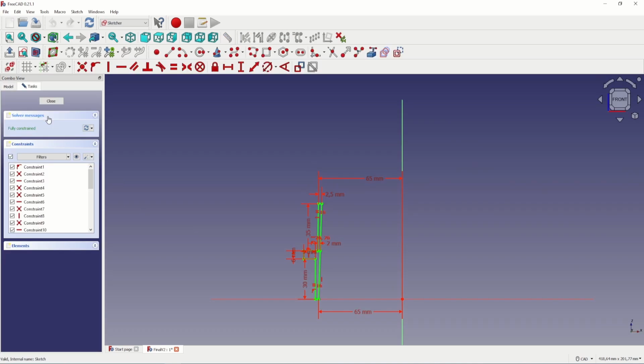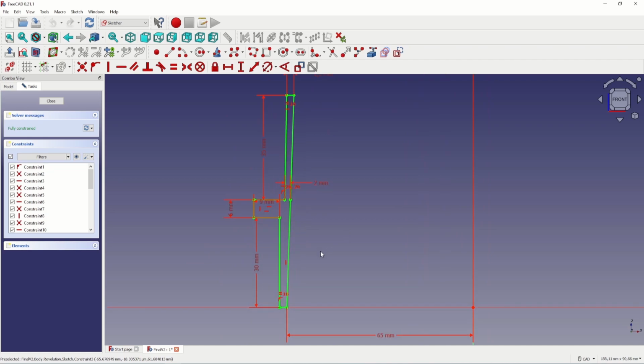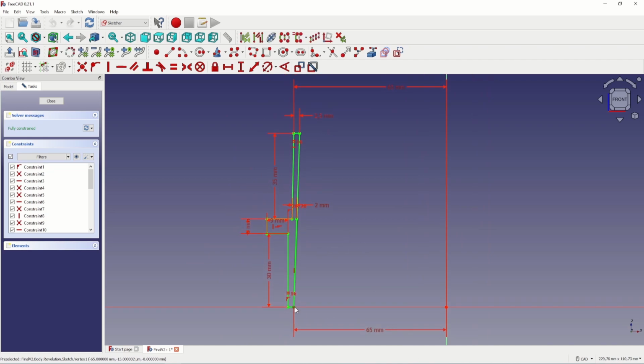So now I will show you the corrections I made. As you can see, the inner radius at the bottom is set to 65 mm. And to fit into the wall socket I have, the outer radius is set to 65 mm as well. The thickness varies between 2 and 2.5 mm, which I think is enough for the part to be stable.